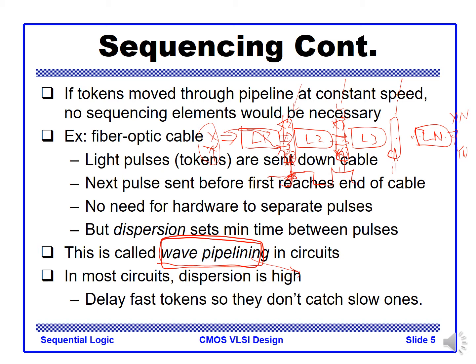The only application currently where wave pipelining is used is memory design. In Samsung memory, they are designing very high-speed logic. They need very low latency. When the input changes, the output comes out very fast. So they design all the data paths to have the same delay, so that they can do a complicated operation very fast in a very short time. That's the only application. For the wave pipelining technique, Samsung is the best.